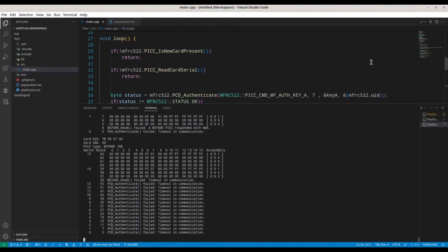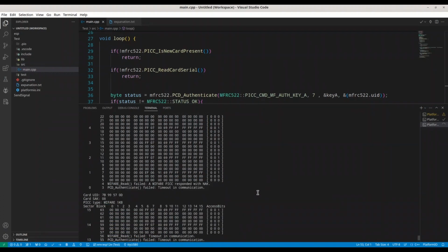Okay. So our data is successfully written to our data bits. You see here with block number 11 we have the old value FF078069, and with block 7 we have EF069169, and we read everything up to block 4. For block 4 we don't have reading permission.